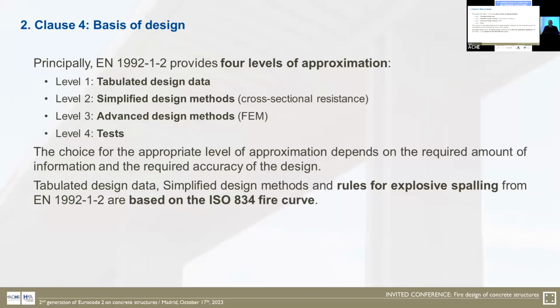And buckling, when you deal with reinforced concrete, is not so significant in ambient conditions, with the exception, of course, of the high columns you find in industrial facilities. In fire, the effects of damage and stiffness reduction can pave the way to unexpected buckling failures, and that's why we had to do a lot of work on columns, and you will see some examples later on.